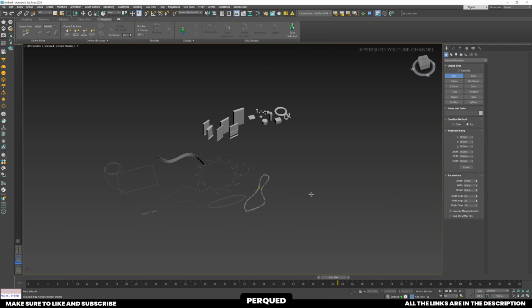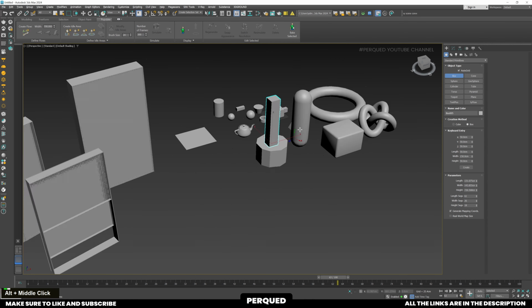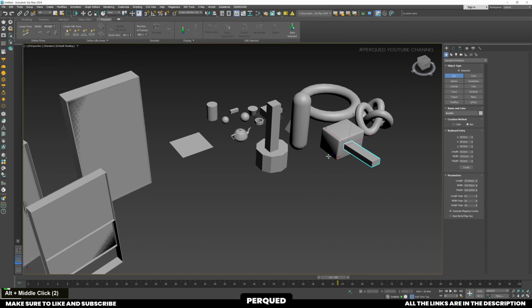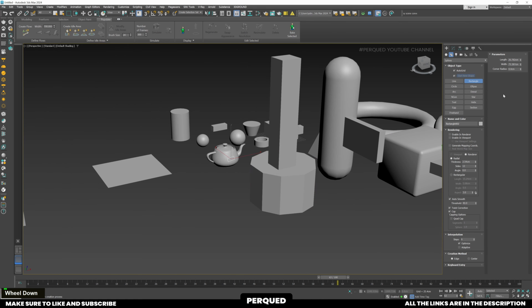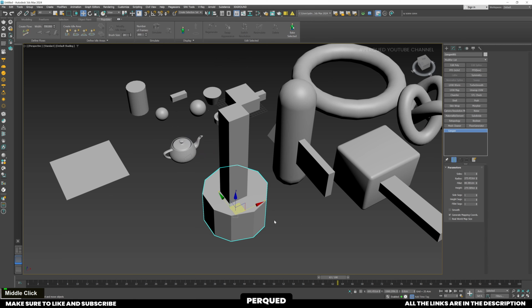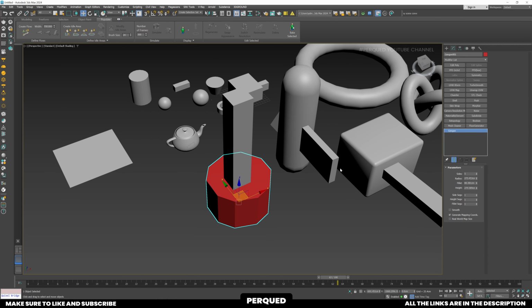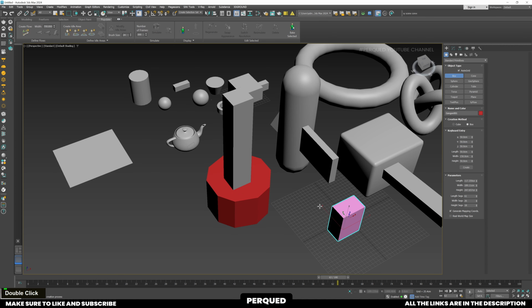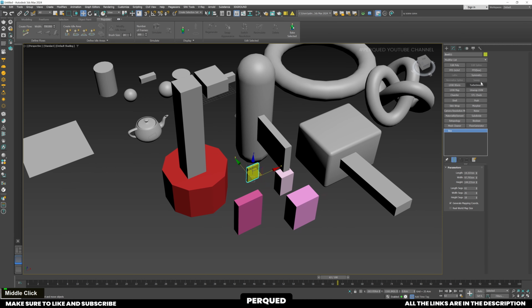While creating any shape or geometry, if you turn on AutoGrid, then that shape or object will be made upon the surface beneath, like I show in this example. This is a quite useful tip for your work. You can set the color of your object from here. And if you don't want 3ds Max to create different shapes in random colors, make sure to turn off assign random color. Then it will create objects in single colors.